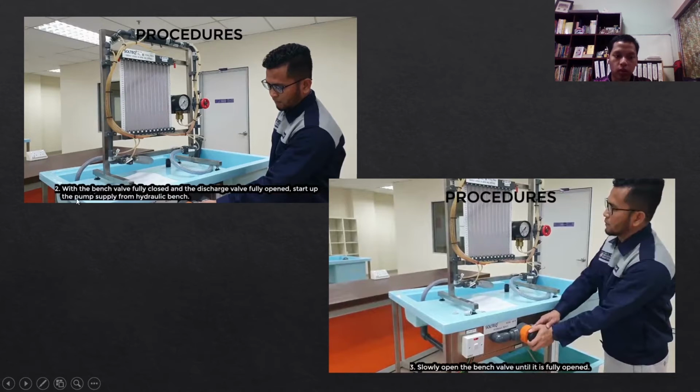Step 2, with the bench valve fully closed and the discharge valve fully open, start up the pump supply from the hydraulic bench. So we need to close the bench valve and open the discharge valve fully, then start up the pump supply from the hydraulic bench.